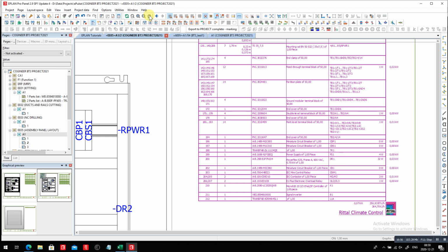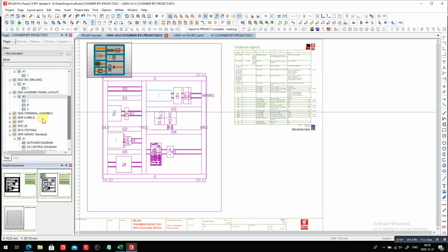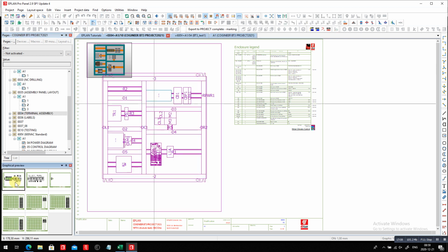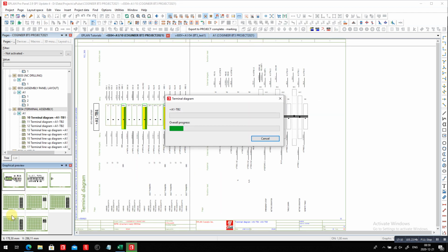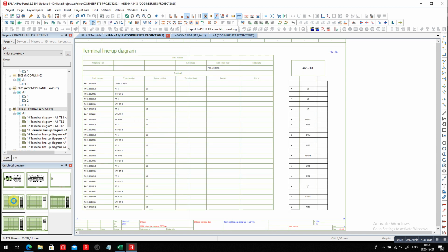And when I say place the components, I also think about assembly of the terminals. So here we have different ways to show you what we have in terms of terminals, what is connected to each terminal, but also how every terminal strip is built, with each part number, clip fixes, and everything else. So that actually helps the electrician build and assemble the terminals. And of course, the labels. Yet the labels, I can do even quicker than this.